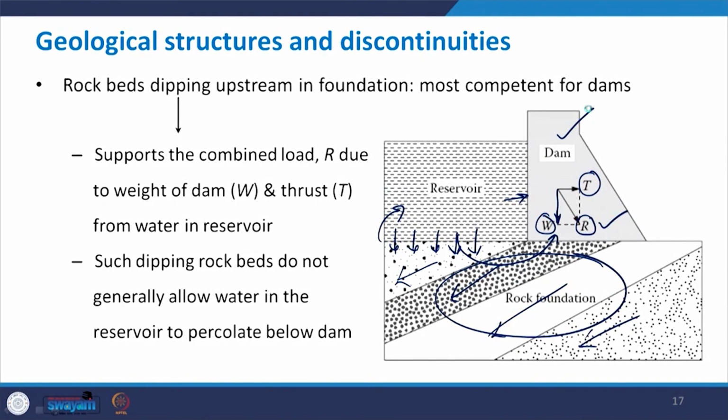What we discussed today are the different types of geological structures, including faults, folds and unconformities. Then we discussed joints, the various elements of each of these structures, and why it is important for us to know the exact features of all these geological structures in order to plan construction activity on rocky strata.